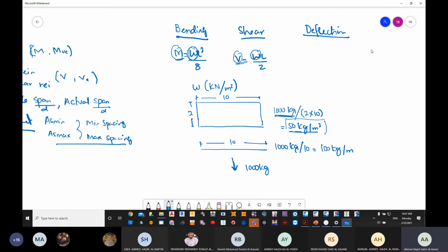of course the slab is going to have a higher weight. True. So since the slab is a large area, normally it fails in deflection. Why is that? Because it's a large area, it has a very huge self-weight.